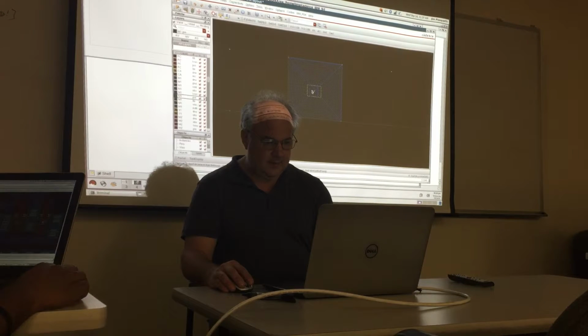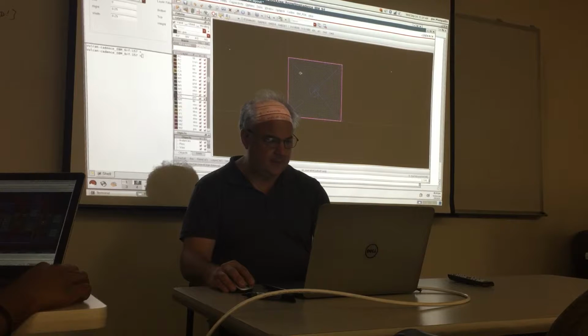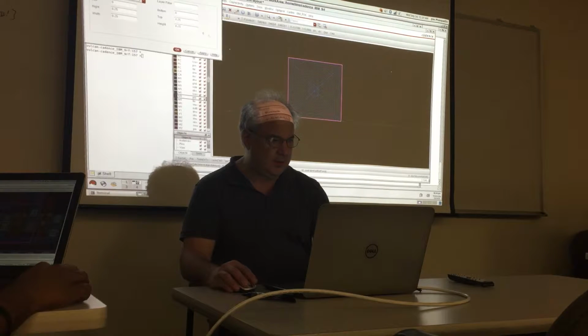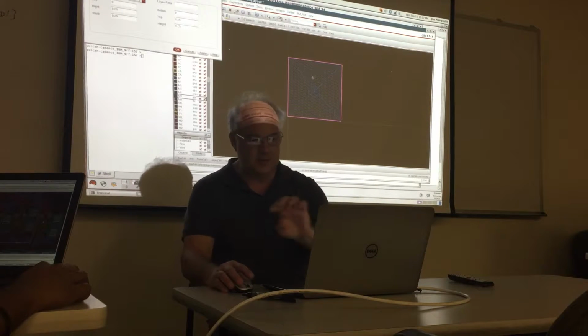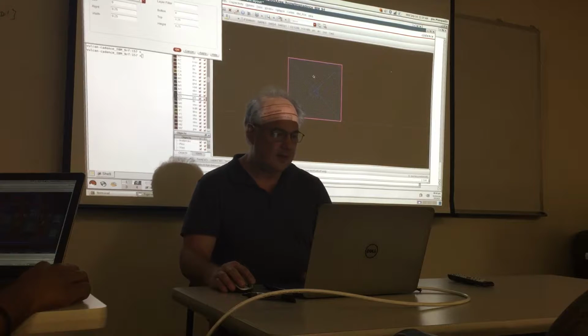It's kind of weird the way Virtuoso works, but it puts this dotted rectangle around the shape. If you click on it, if you do Q, you can tell which one you have when things are superimposed in the Z axis, which is the axis you can't see.